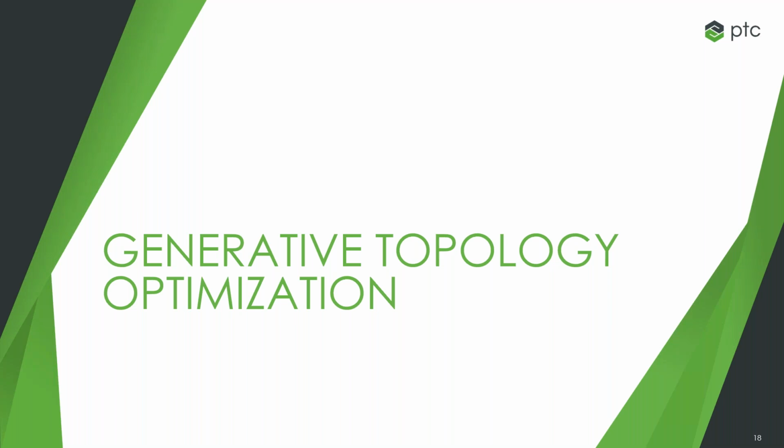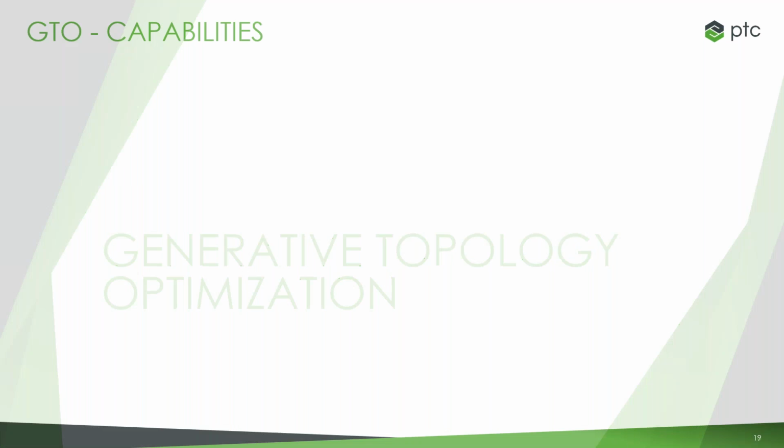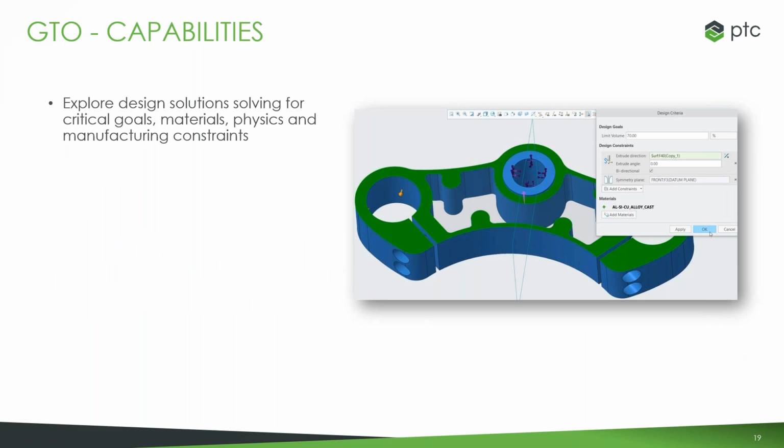And one of the biggest developments with the release of Creo is the introduction of generative topology optimization. Generative design, if you haven't seen it, autonomously creates optimal designs from a set of design requirements that you lay out for your study. Working with this in Creo, you're going to be able to specify your requirements and the goals that you want to work towards, and the generative engine automatically produces a manufacturable design, either as a start point or even as a final solution.